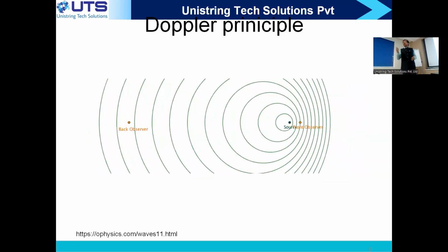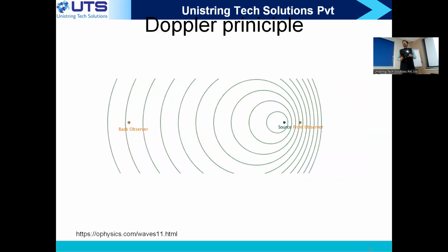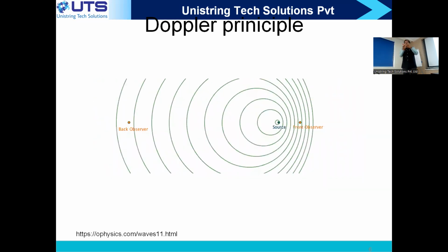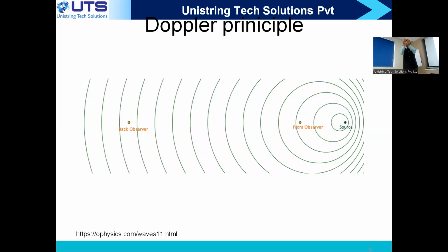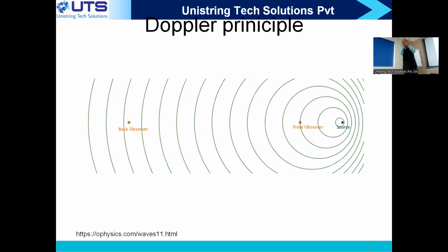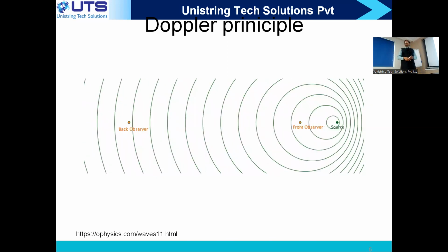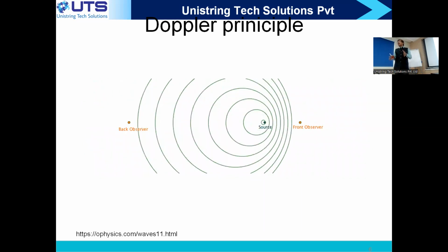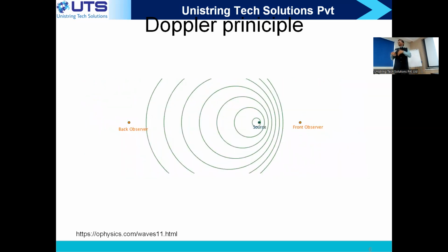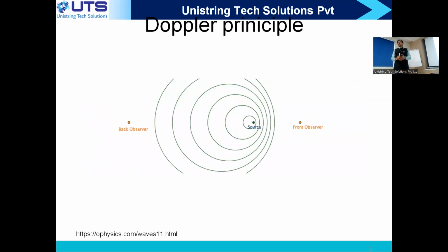Are you getting my point? Do you agree with this point: when a drone is coming towards me, the drone may be moving at 10 meters per second, but the blade that is rotating is moving much faster. So the blade is like this. When the blade is rotating, maybe at some 1000 RPM, the tip of the blade is actually hitting my electromagnetic wave much faster. It creates a different Doppler. So a deeper understanding, and building an application with the deeper scientific aspects, for better versions and better features of the product, will require visualization of the subject concepts.